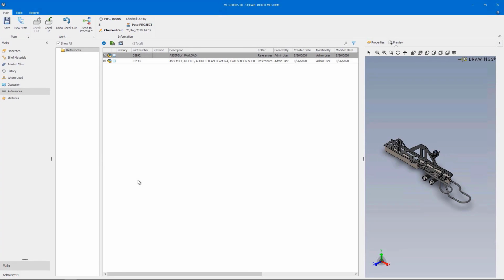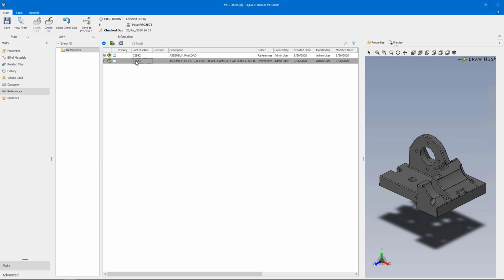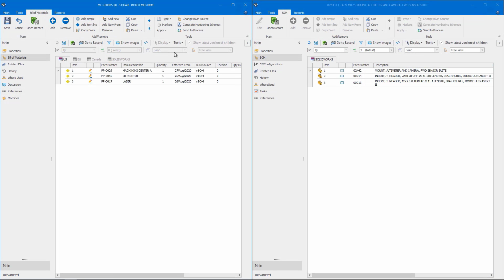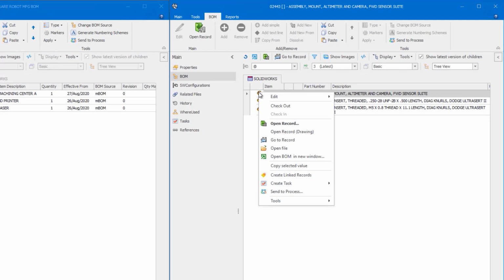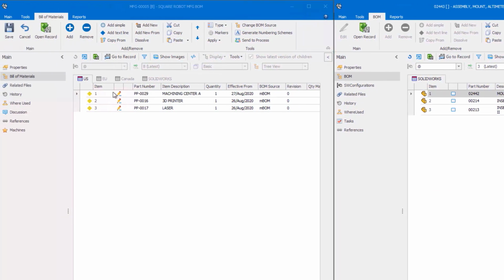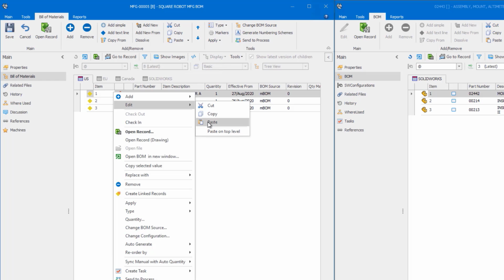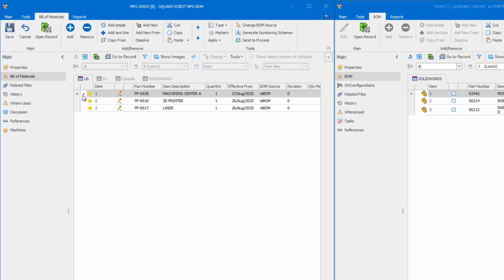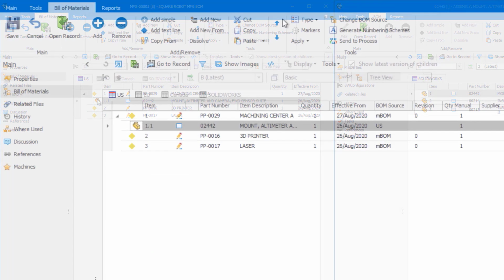Items are a powerful way to collaborate on design data and manage it. The item record has a reference to a number of SolidWorks assemblies that need to be consolidated into a manufacturing bill of materials. Modeless windows now allow you to open multiple records and work in both at the same time, facilitating the ability to copy and paste from one bill of materials to another.